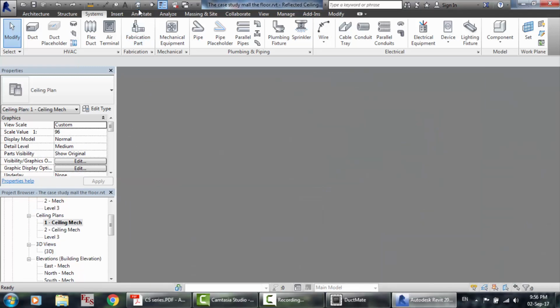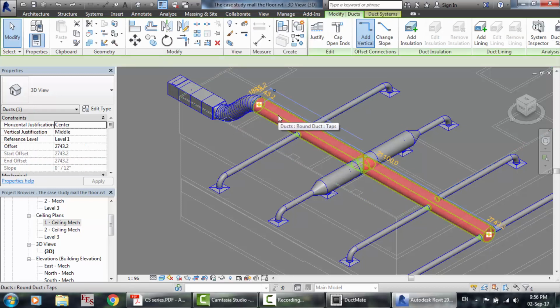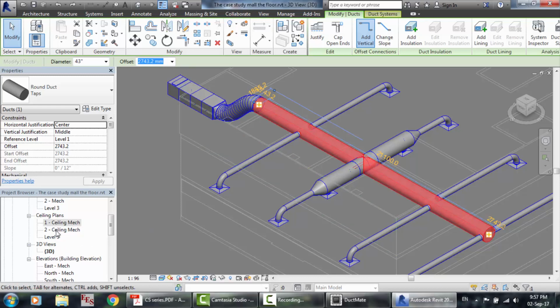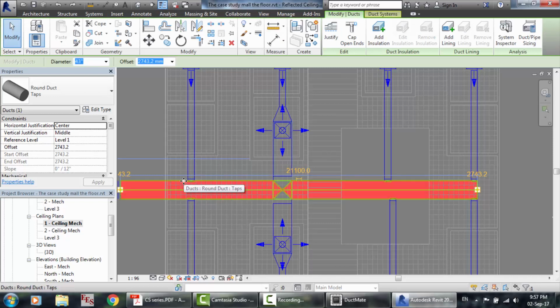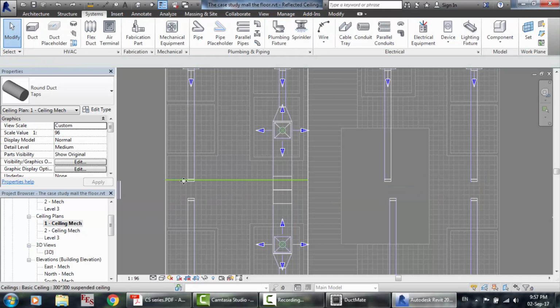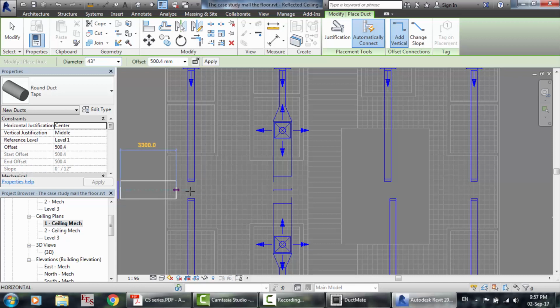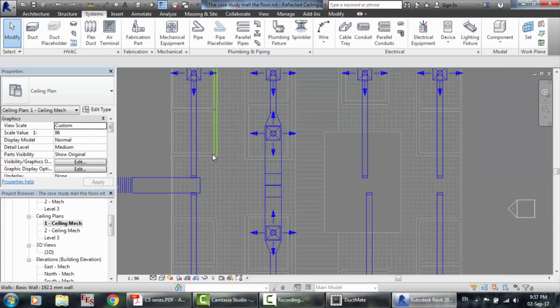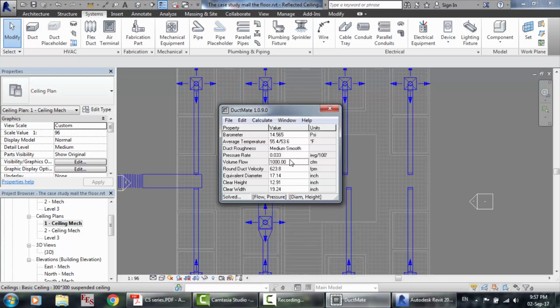Okay, now, gentlemen, we have this system, but we have to resize the ducts. So we have to, unfortunately, delete this duct because we do not need its size. 43 is not, we do not require all this. So get a duct 43 to here, and then this duct has to be reduced. Now we need 1000, we need 8000,